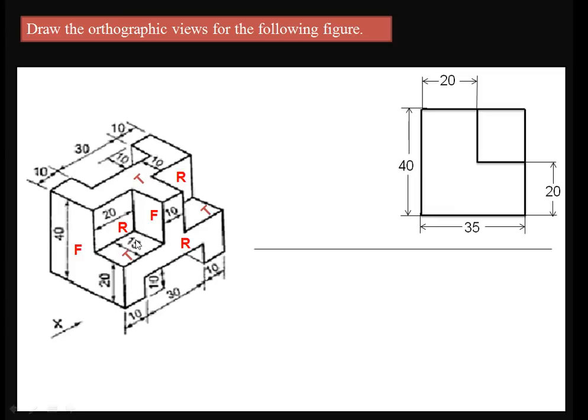In the front view we cannot see, but we need to represent on the front view. So what are those edges? One is this one, this corner point. Observe the cursor where I am placing my cursor. Here at the back side of this surface there is an edge with a particular height. That is at a distance of 10 from the last edge of the surface.